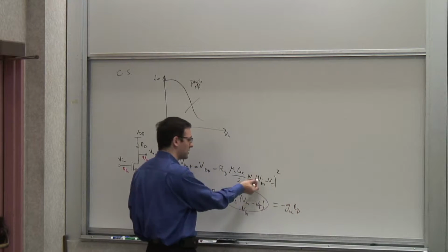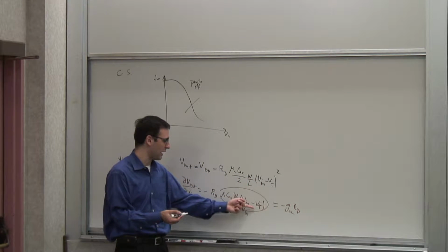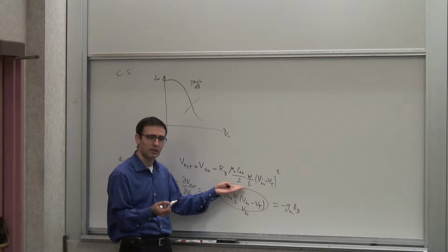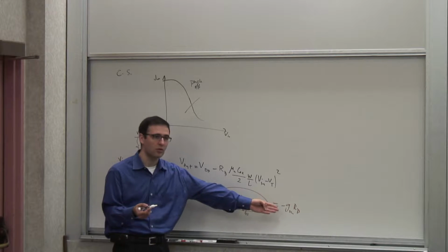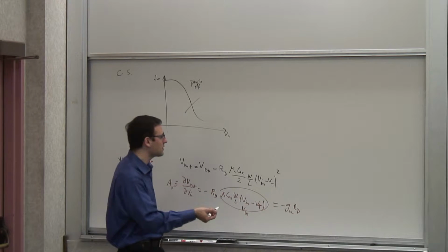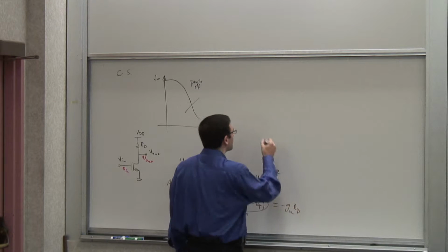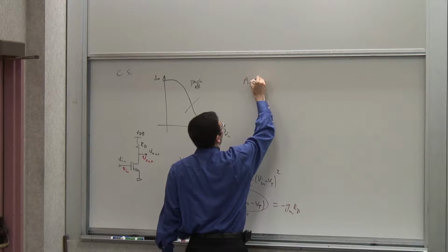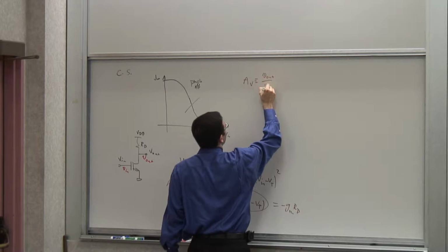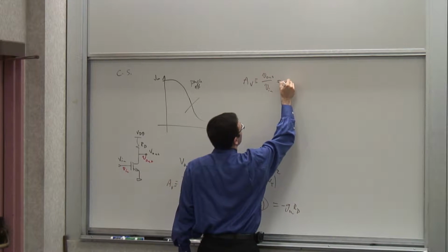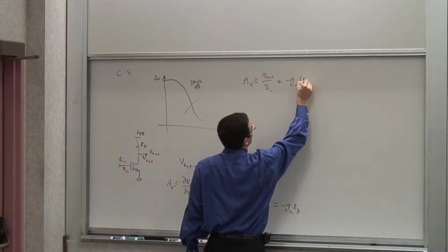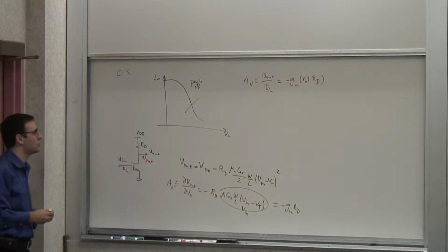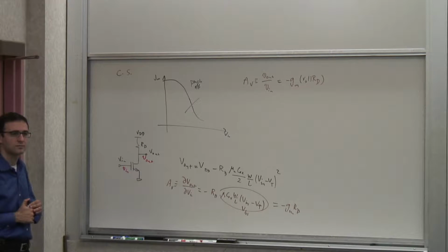And of course, in the original equation, and the resulting equation, we don't have the channel length modulation taken into account, and therefore you don't see RO in this equation. We also did the small signal equivalent model that gave us a more accurate result. So basically we said, well, if you really take that channel length modulation into account, Av, which is defined as the ratio of V out to V in, would be minus gm (RO in parallel with RD) for a non-degenerate common source stage, right?